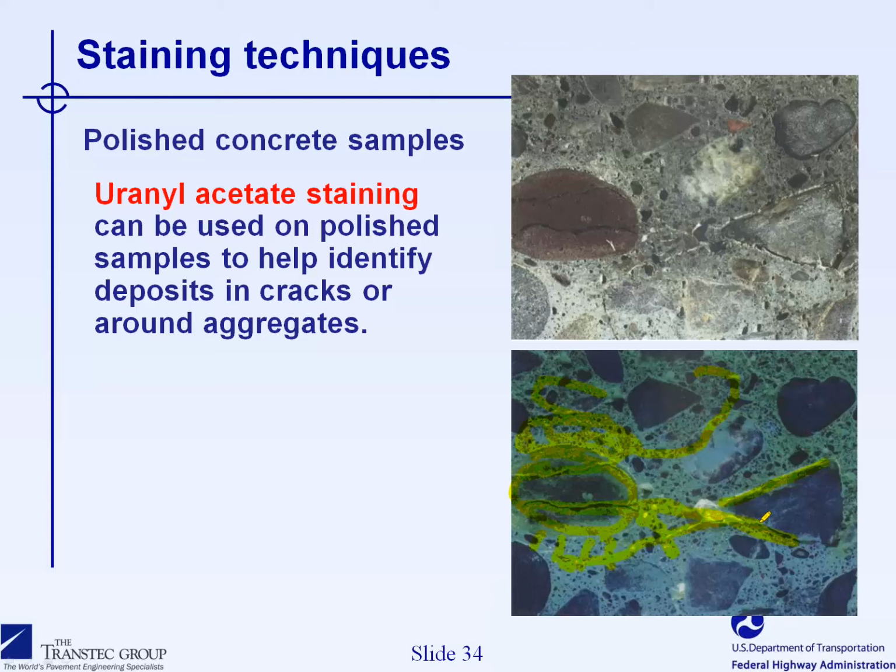Okay, thank you. The next question is, how can you tell visually if the cracks are ASR or DEF cracks? Basically, it is based on a petrographic examination of concrete cores. First of all, obviously the source of the problem is not the same.